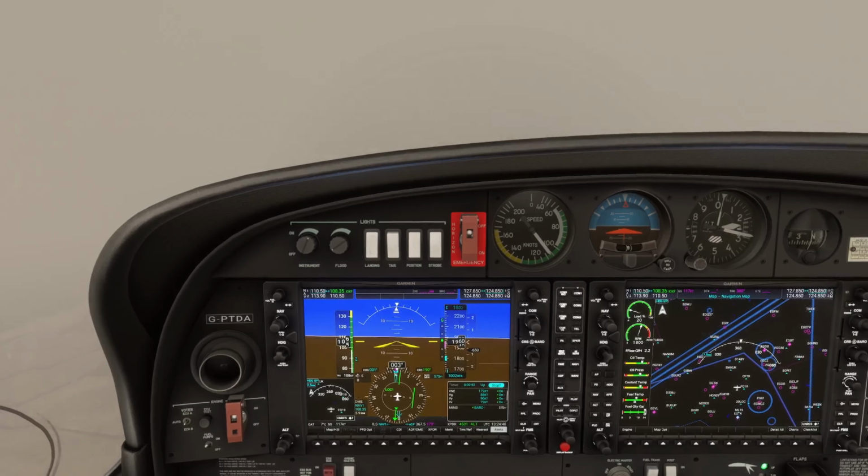So we're now 0.2 away, so 6.5, we've twisted, now we're turning. Don't need to time and no need to talk at the moment. So we're just maintaining the turn now, and we want to roll out and wait to intercept the localiser.